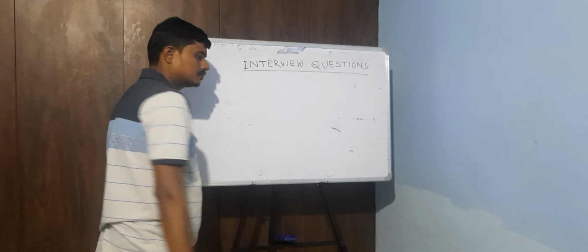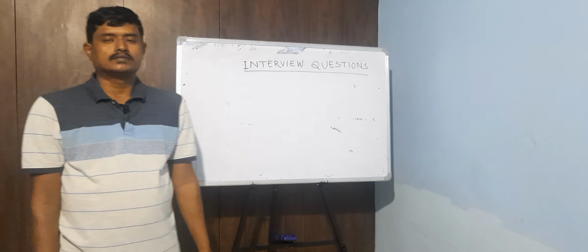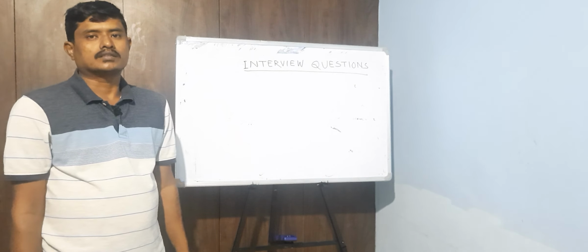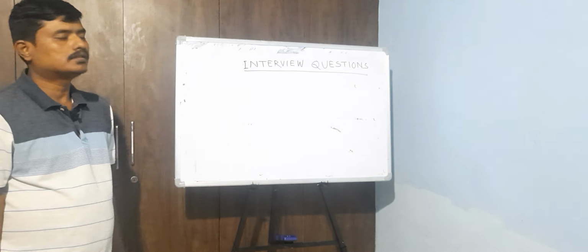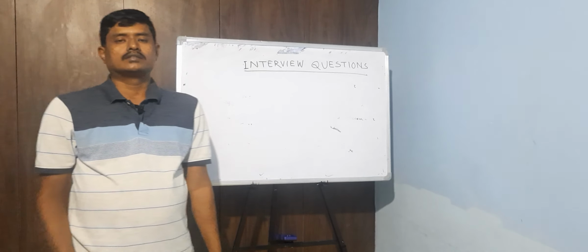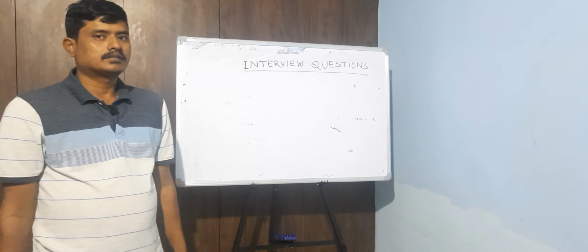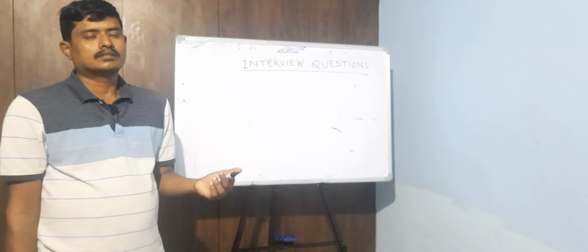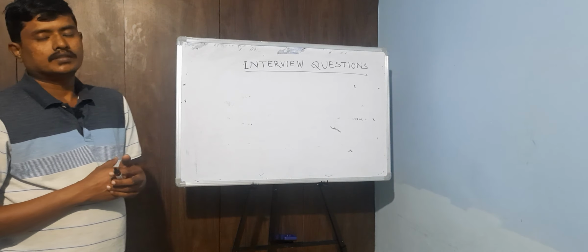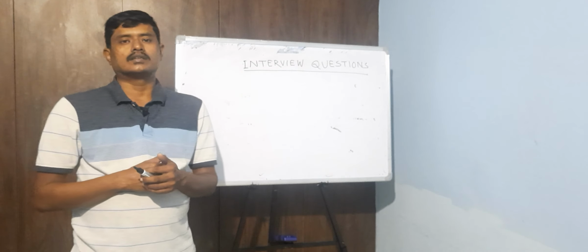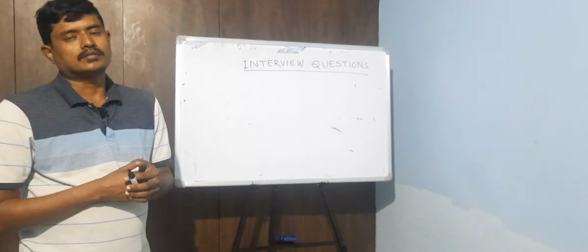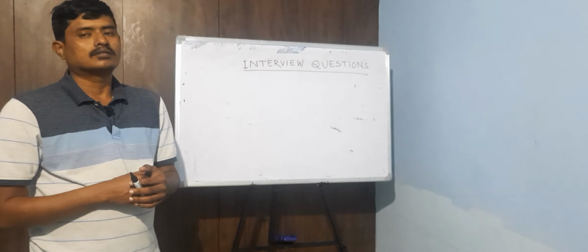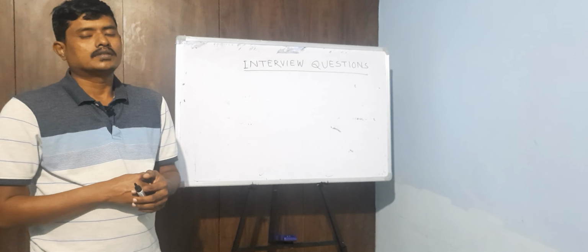So again we discuss how many earthings are provided to a transformer. Basically, 4 earthings are provided. 2 earthings are for the body, 1 earthing is provided for neutral earthing, and the other earthing is provided for LA earthing.